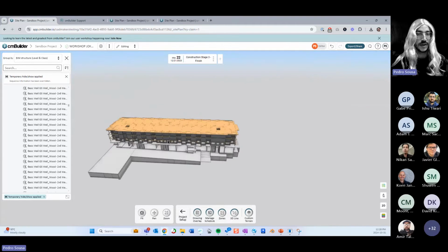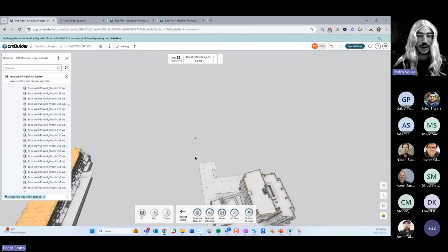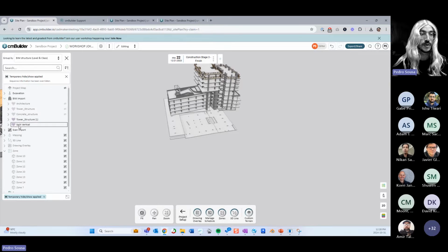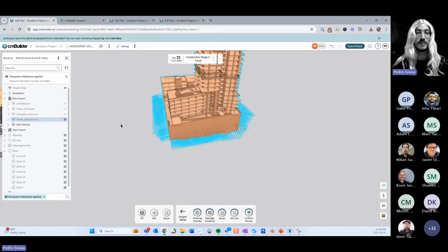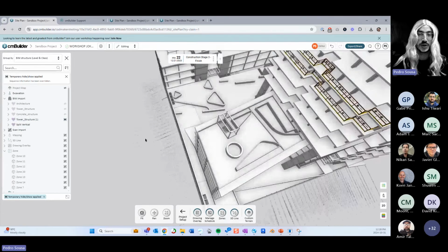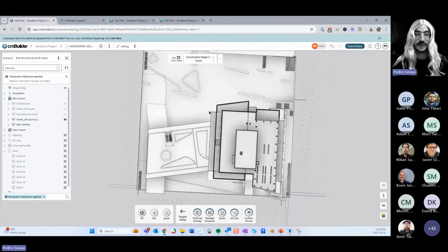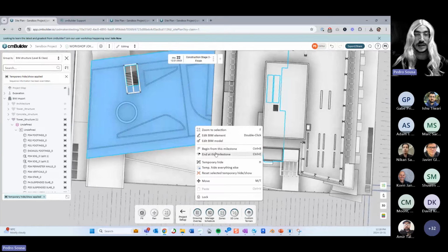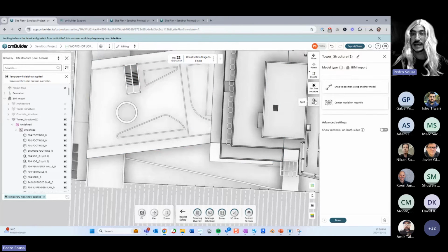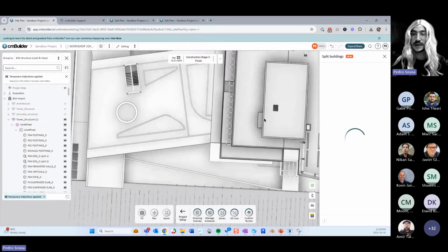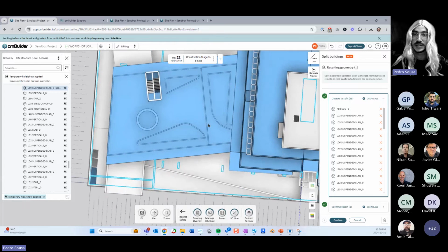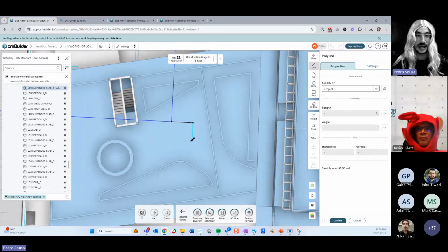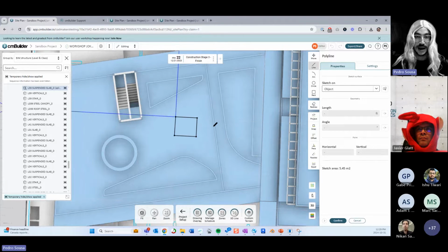Cool. Another big use case for this tool is to create openings for cranes, right? So if I show this whole model over here, and I want to create an opening for a crane, let's say at this location or maybe at this location. So what I do, I simply go ahead and continue with my split, and then I can add a split geometry again over here. And from this point onwards, I'm going to create a line. And from this line, I'm going to draw a closed shape that represents the opening for my crane.